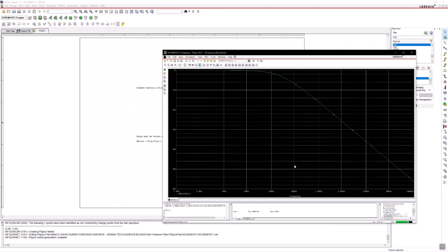Now, as soon as you make higher-order filters, you've, of course, introduced complexity. Now, this always gets people at first: 0 decibels refers to that there is no gain. 0 decibels is not multiplying by 0. Because if the output is the same as the input, then V out divided by V in is 1. And the log of 1 is 0.